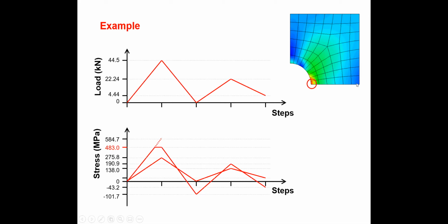So you need to calculate the stress load value. You need to apply the local area yield point stress. Did you get what I'm explaining? So you can calculate. So in this example, would the local area yield point stress be 483? Yeah, local area stress, if it reaches 483, you can't preload above that level.